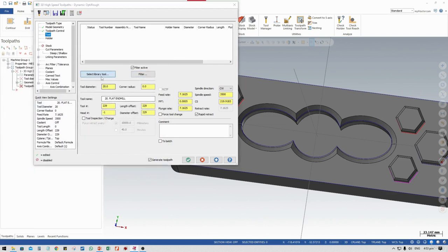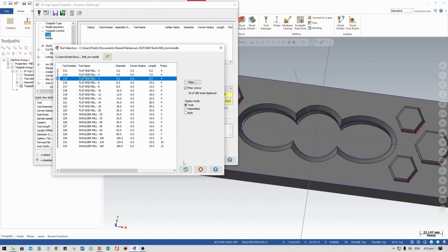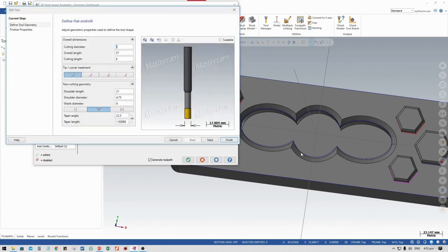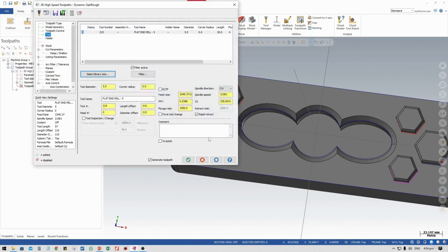And select the 5mm end mill. Okay. So I've just given you an idea of how we can select a cutter. You have to select the cutter according to your design specification. Okay. So cutter diameter is 5mm, cutter length is, like, we'll define that my cutter length is 30mm. Okay. It's just to give you an idea. And the 80mm. Finish. About the speed, I'm giving you 10,000 RPM spindle RPM, and 3,000 millimeter per minute feed. And the plunge rate is 300mm. Give the tool number 1 for this operation. And all these things, we have just done.